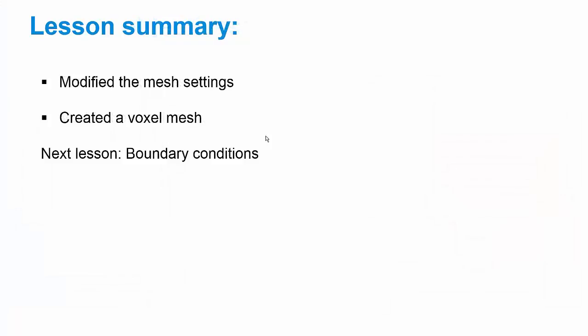So just to summarize what we went over, we covered how to modify your mesh settings and how to create a voxel mesh that's suitable for the analysis. In the next lesson, I plan to cover how to edit boundary conditions in the analysis.